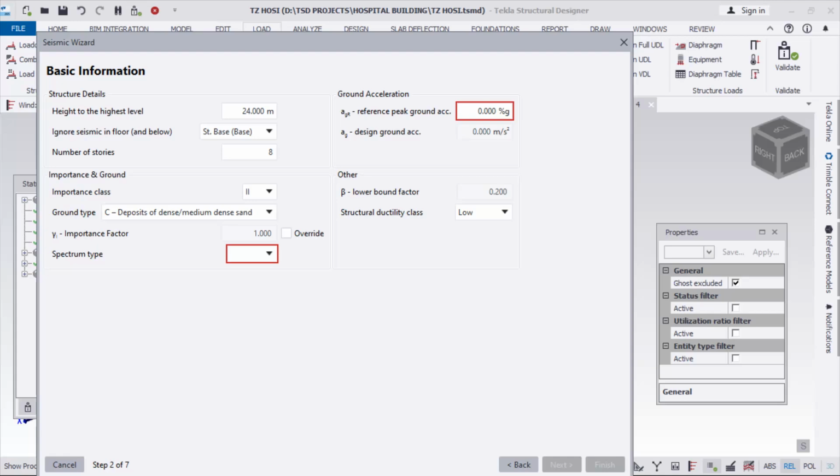And as I have said, it is usually the upper floors that contribute largely when it comes to the seismic forces. So when you're calculating the mass source, we normally consider the floors that are above the basement.